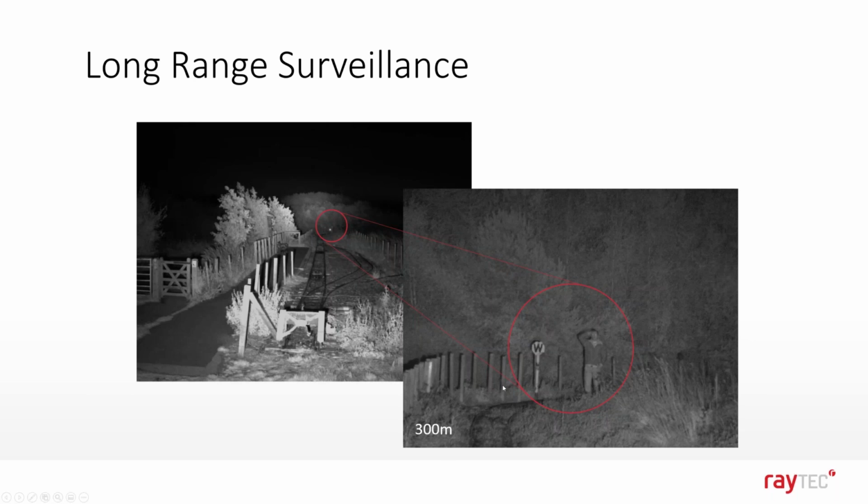Because what you find a lot of the time is, if you're using either a low quality infrared that's not matched to the camera, or a camera with integrated lighting, what will happen is usually when it zooms in, it looks very good because it's got a narrow angle light that'll zoom in to the far distance. But when you put the camera back to its wide angle, it's going to be quite spotty in the middle and dark on the outsides, which is certainly what you don't want to get a good image.